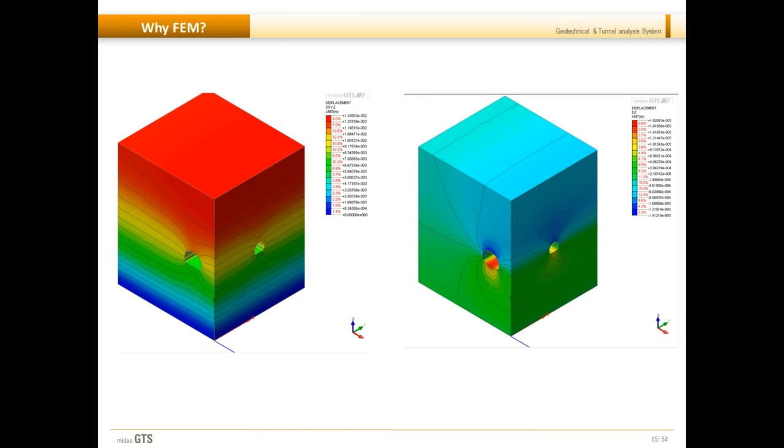It's not considering how the forces from the excavated soil strata are distributed onto the lining to support the overhead structure. So this clearly shows that if you have one problem and you do it with construction stages and without construction stages, you will be able to see the difference. And obviously, since the construction sequence is more realistic, the results from construction stages will give you confidence in your results.